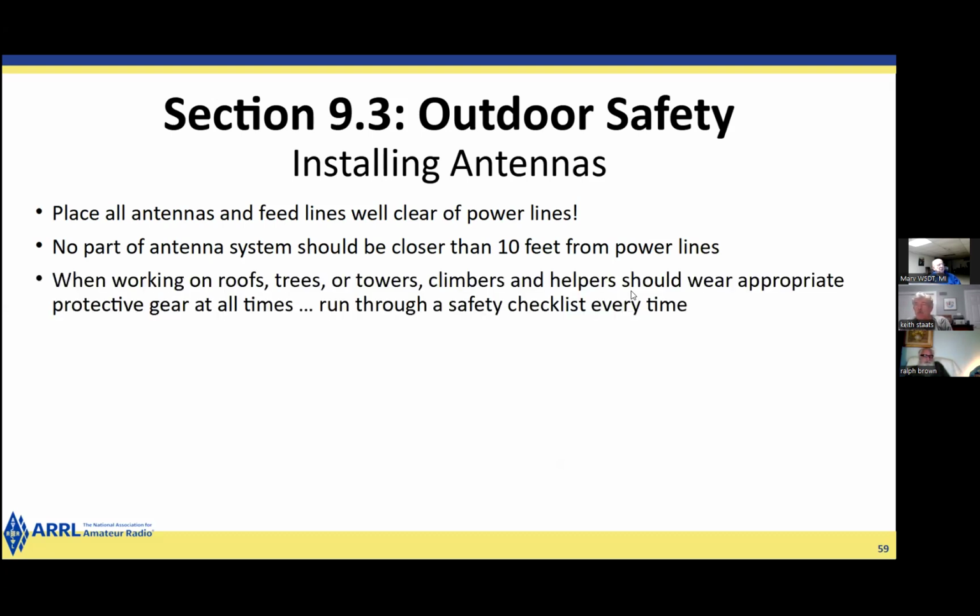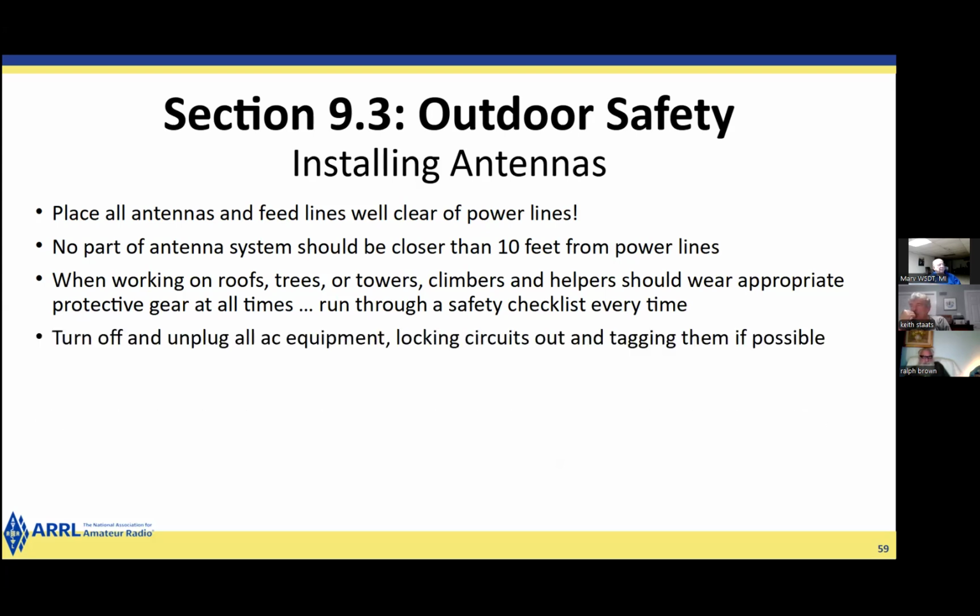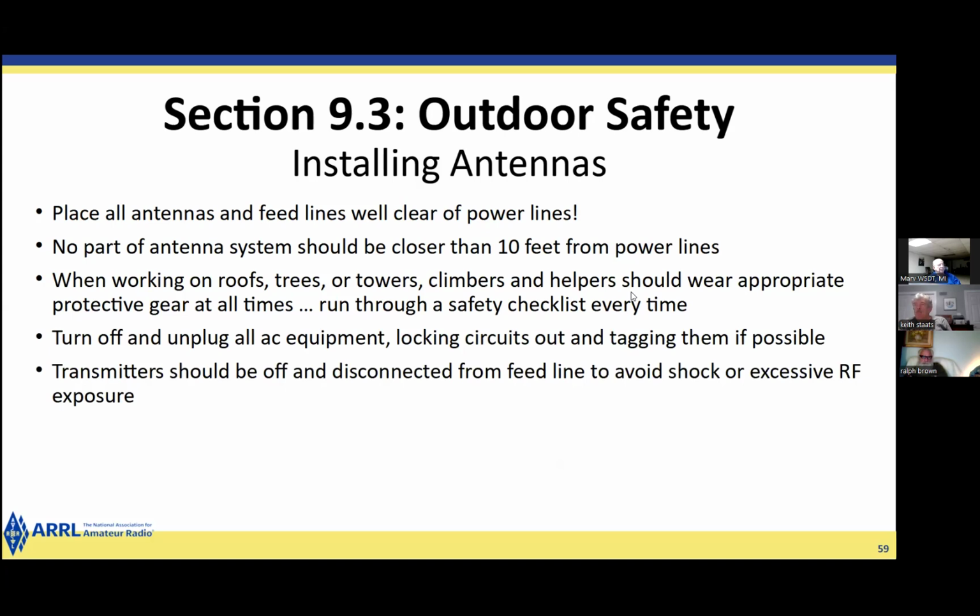When working on roofs, trees, or towers, climbers and helpers should wear appropriate protective gear at all times. And you should have a safety checklist. To turn off and unplug all AC equipment. You lock out the circuits and tag them if possible. Transmitters should be turned off and disconnected from feed lines to avoid shocks or excessive RF exposure.